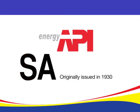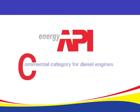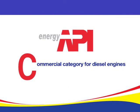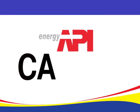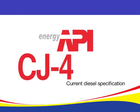SA was originally issued when API was created in 1930, but as of today, SN is the current S category specification. The C category represents the commercial category for diesel engines. CA was originally issued in 1959. As of today, CJ4 is the current diesel specification.